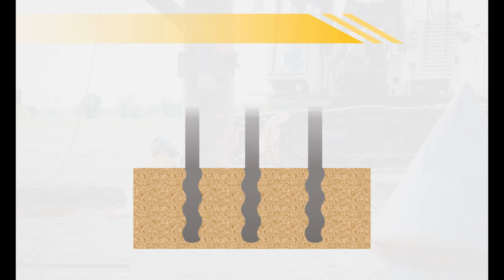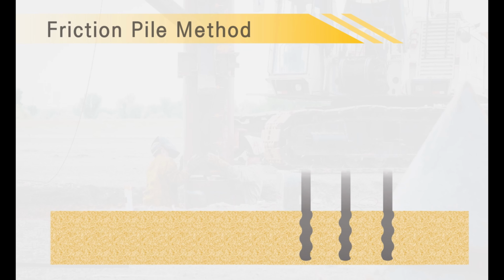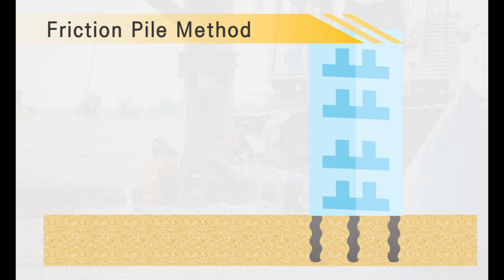That is to say, friction-bearing pile foundation does not necessarily need a strong layer of ground at the end of the shaft, because it transfers weight laterally into the surrounding ground throughout the length of the pile itself. That is why this method had an advantage on our site on the seashore. So theoretically, this was the best method to use in our Capitol Gate Tower if it was standing straight.